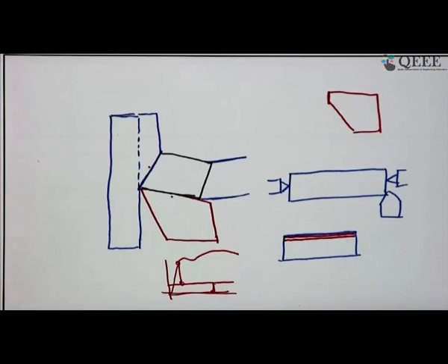It is not only for those who are involved in manufacturing by machining, grinding, but it is also important after this treatment, when it is going to be used. It is not just on a machine surface, it is going to be used in making some machine component, say spindle, shaft, some rotary component, and in that case if this surface stress is not properly monitored or conditioned or neutralized, or if we do not induce some compressive stress, then it will be aggravated.